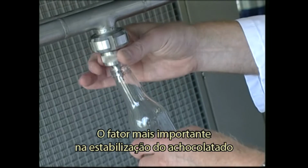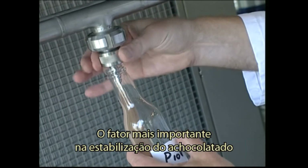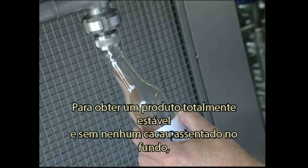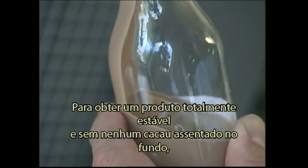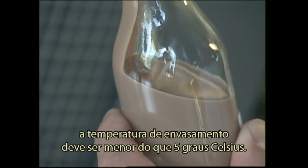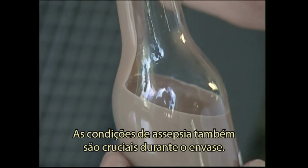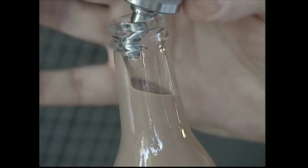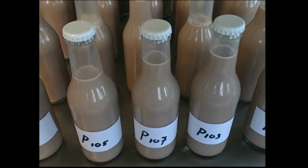The most important factor in chocolate milk stabilization is the filling temperature. To obtain full, stable chocolate milk without any cocoa settling on the bottom, the filling temperature should be lower than 5 degrees Celsius. The aseptic conditions are also critical during filling. Cross or after contamination can cause severe product spoilage.